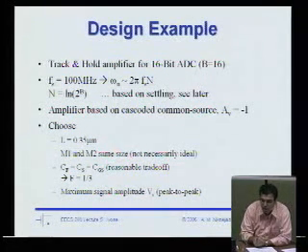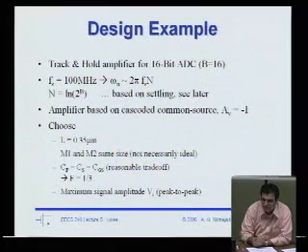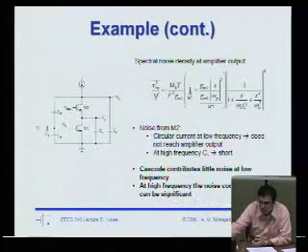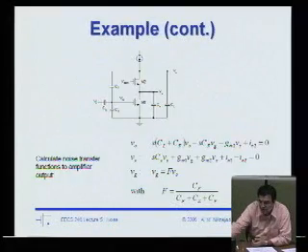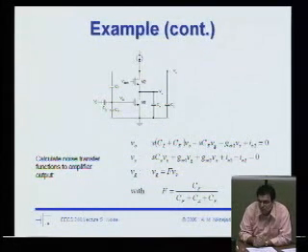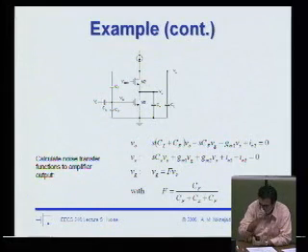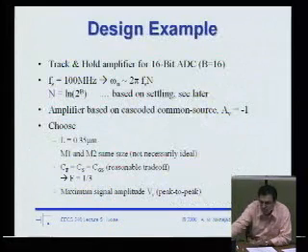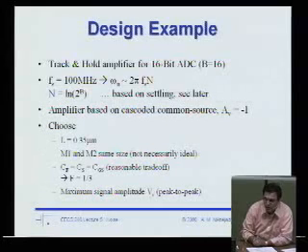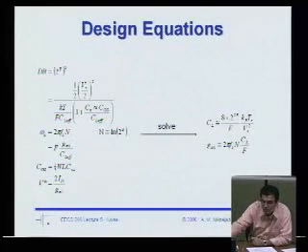We're going to do a cascode amplifier. It's probably not the best choice, but it does keep things simple. And so in this equation, there's this factor F, which is the ratio of CF to the sum of all these capacitances, CF plus CS plus CP, making the assumption that they're all equal gives us F of 1/3. Okay? And so then we plug in.